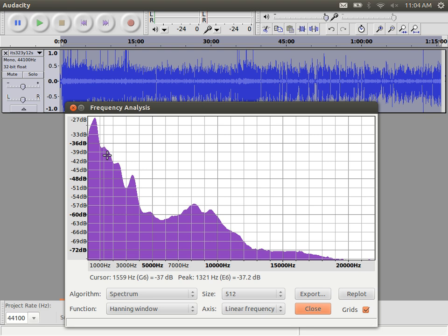In practice, we see that in this example, the signal strength is strongest here. Down here is very, very weak. There are small components, but a very, very weak signal up to 20,000 hertz. Maybe there's even some out here. In practice, we define some cutoff, and we get what's called the effective bandwidth. We say that if the signal strength is below some level, we will ignore that.